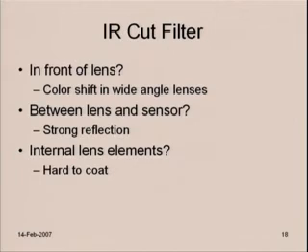Yes? So if you're not taking wide angle, is it okay to put the IR at the front of the lens? Yeah, actually it's a really good solution for a telephoto lens to put an IR cut filter in the front, because the angle isn't changing very much. The advantage is that it keeps this reflective surface far away from the sensor, and as a result, which I think is coming up in a moment, the total amount of light reflected back to the sensor is lower, which is what you want.